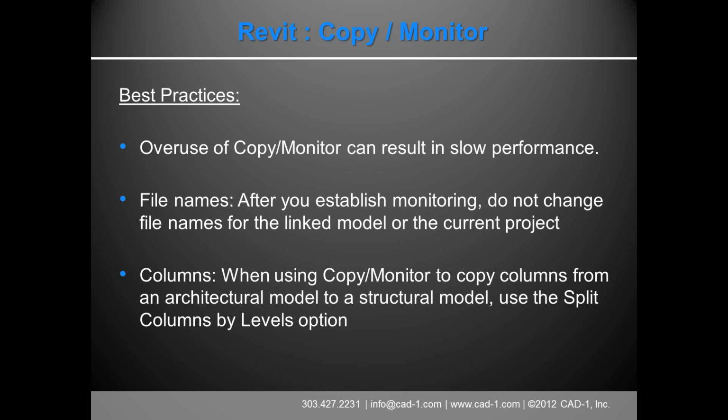You can also, kind of a trick for the MEP people, if you get a file from the architect, or download it from a manufacturer, and the manufacturer, maybe they're not using Revit, but they're making Revit families, and so they made all their lights ceiling hosted, or their electrical items wall hosted. You cannot use those in your MEP file because you don't have a live wall or a live ceiling. You only have a linked file.